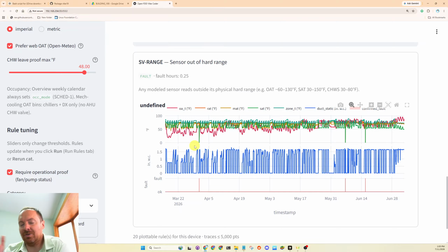We can start taking notes. We should be taking notes on reducing the air handling runtime first of all, then reducing the chiller enable. That's another ECM. And let's keep on compiling. We can basically compile a nice list, and this could get sent off to the client, like, these are the things wrong with the building that I've noticed.